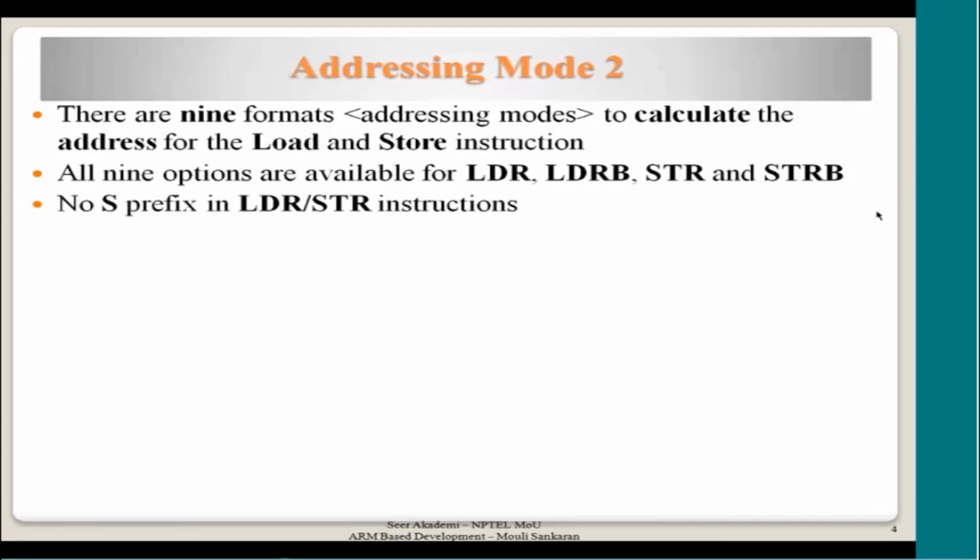One more important thing to remember is that there is no S prefix for LDR or STR instructions. You remember what S is: whether the instruction can affect the condition flags maintained in the CPSR or not. In a RISC architecture, all the operations within the processor are done only when operands are from registers, correct?